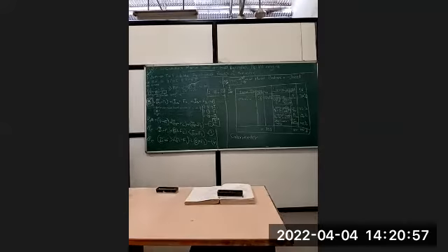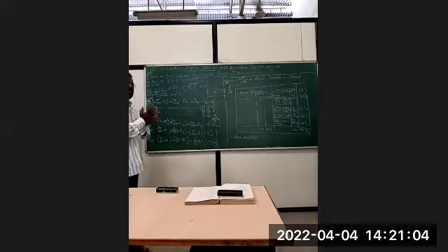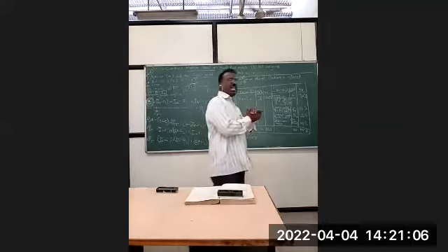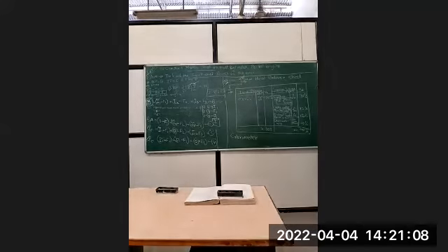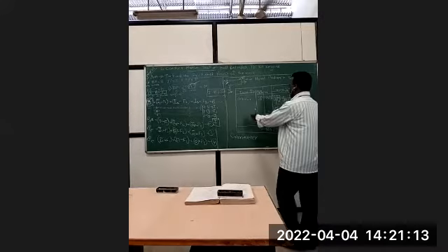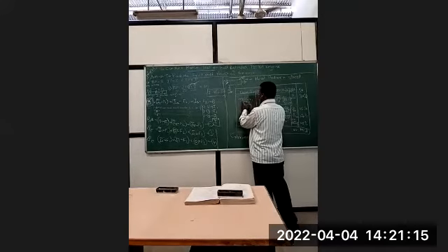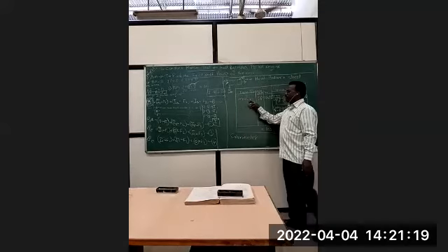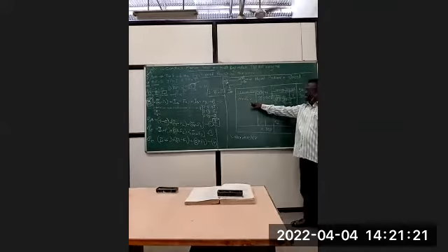So this is how we go for heat balance sheet. In the heat balance sheet, we are trying to balance out, or find out, where the energy is going, whatever we have given to the engine. First we will find out where the energy is coming from. Energy is coming from the fuel. So the fuel energy is equal to MF into CV, which is the input to the engine.